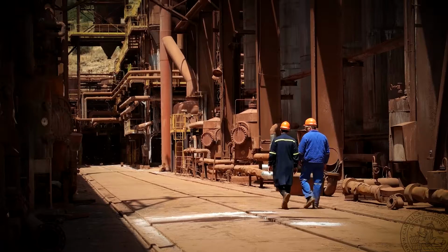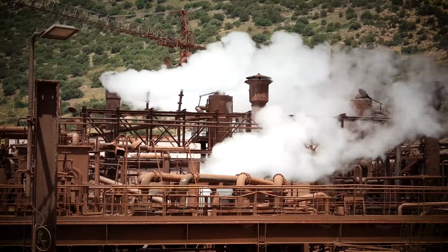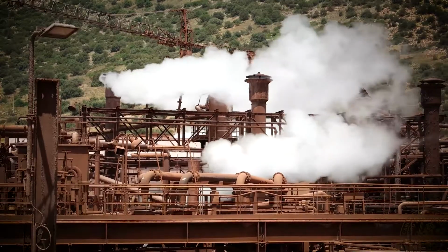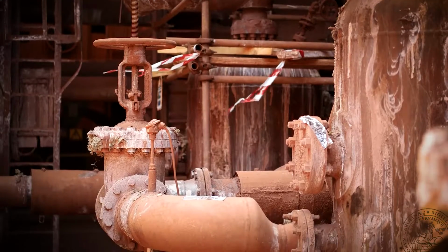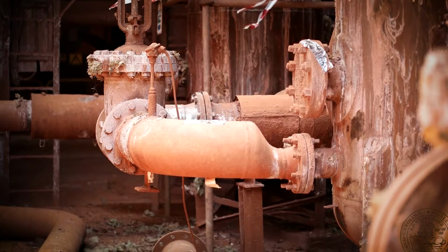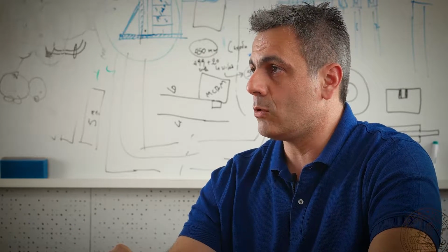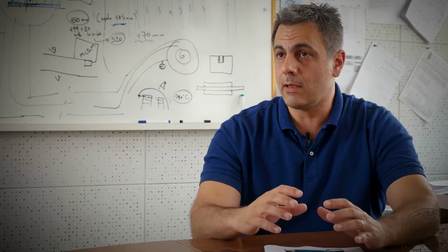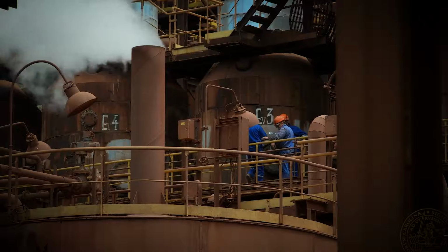The digestion unit consists of 2 lines of autoclaves. Each line has about 20 autoclaves. We increase the temperature slowly from 70 degrees to 255 in the autoclaves. And then we keep the slurry at this temperature of 255 degrees for about 30 minutes in order to be sure that we have extracted all the alumina from bauxite. Then, in order to keep the slurry at this temperature, we have increased the pressure already. So the pressure in the autoclaves for the slurry is 40 bar.